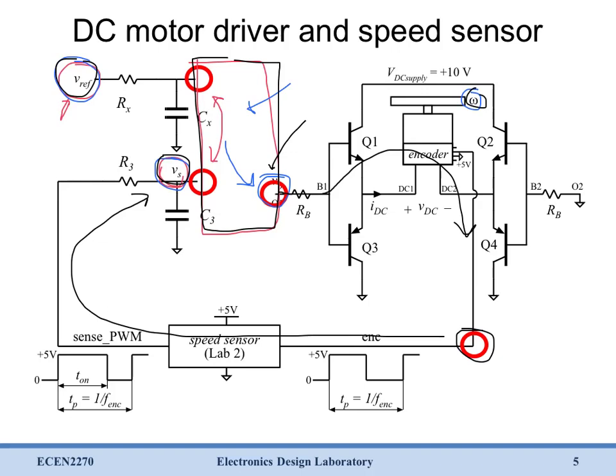We'll model our motor driver and our motor to get a relation between VO and omega. We'll model our speed sensor to get a relation between omega and Vs. And then we'll generate a controller which will take Vref as an input and generate a necessary VO.